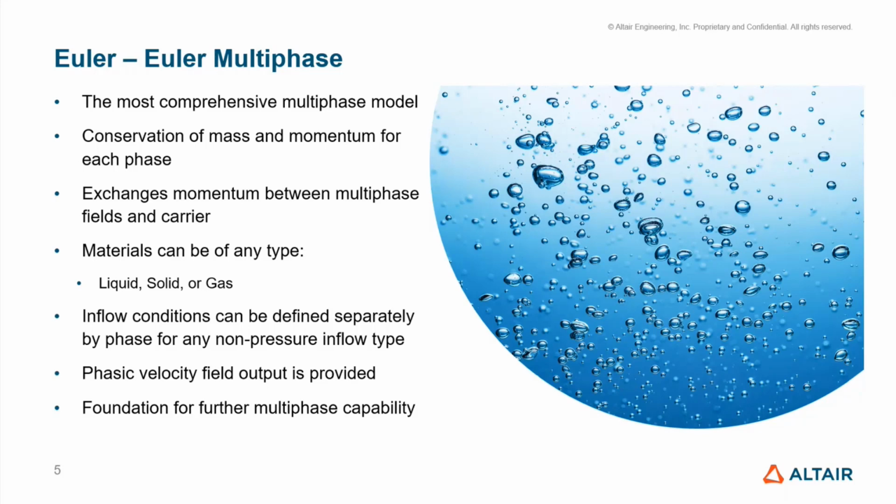Dispersed materials can be any type: liquid, solid, gas, because each phase is tracked separately by its own momentum equation. The velocity of each phase can be defined separately at inlets for any of the non-pressure inflow types. It also allows for the output of specific dispersed field velocity. And finally, it provides the foundation for further multi-phase capabilities.